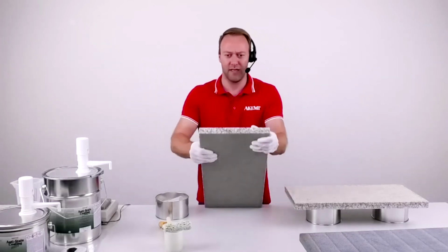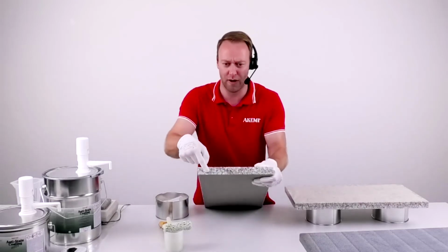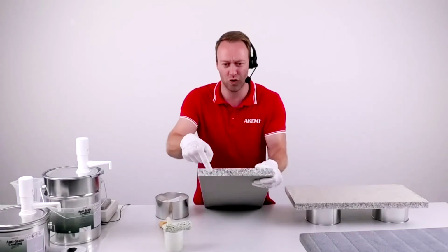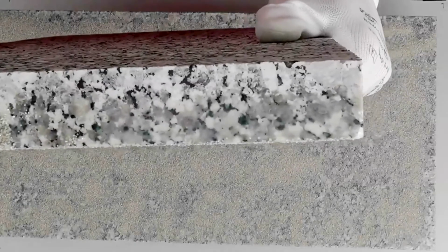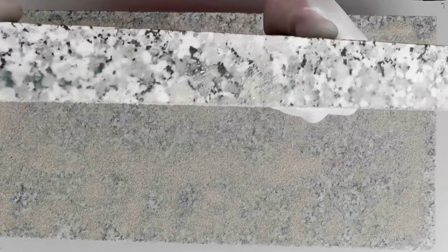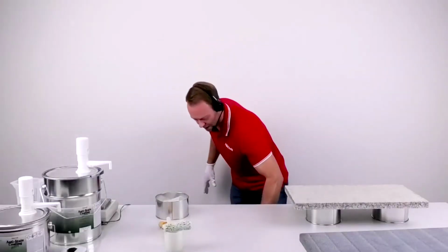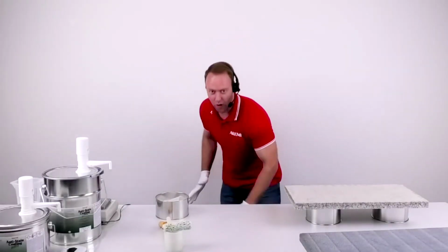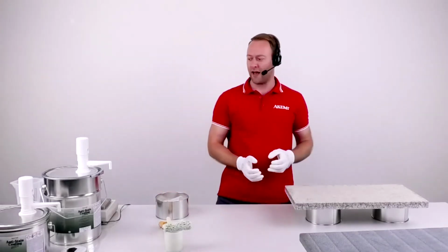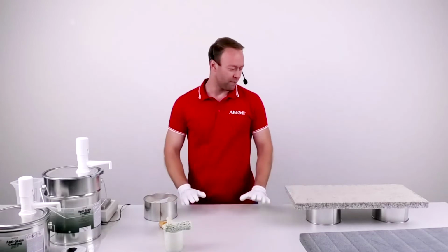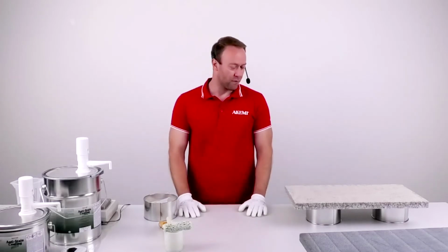I think you can see here that we also covered about a half to two-thirds of the side with coating. I hope you can see what is coated and what is not coated. This is completely enough. Here I can put it in water, no problem, or in soil or in Portland cement. I don't care, and the stone does not care. There will be no staining from the backside.